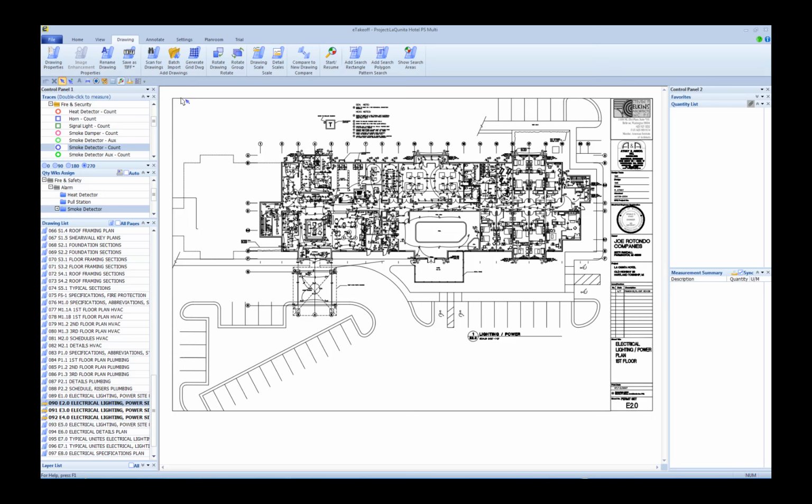Pattern search allows you to predefine search areas on the drawing. You can do that with a 2-point rectangle or with a multi-point polygon. I have already selected my search area, which can be seen by clicking the Show Hide button here. You need only to designate your predefined search areas once. Dimension remembers the setting for future searches.